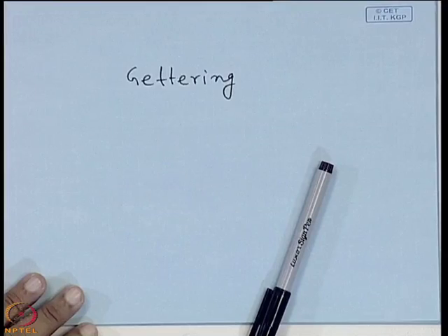Some stress it will provide. So, the stress will be relieved only if some dislocations or defects are formed in the material, and those defects and dislocations trap the impurity. When we talk about gettering of impurity, where will the impurity go? The impurity will be trapped or taken away by the defect or the dislocation in the material, but not at the surface, away from the surface.